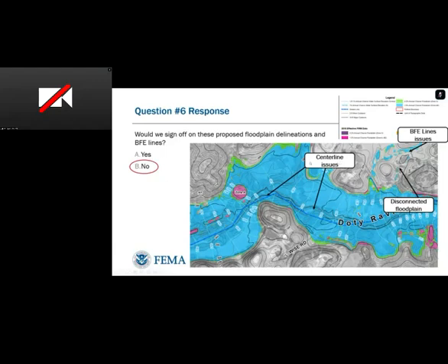Additionally, there are several centerline issues, and this is somewhat unrelated, but is really key when reviewing topographic work maps. If you see their contours here in the terrain, we can see exactly where the stream goes, but it is not where their stream centerline is going. And that's really important when they are making these calculations.